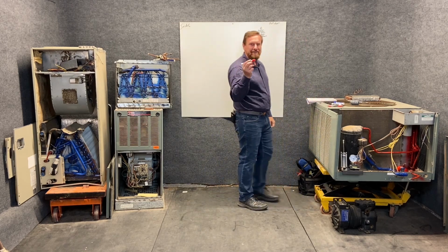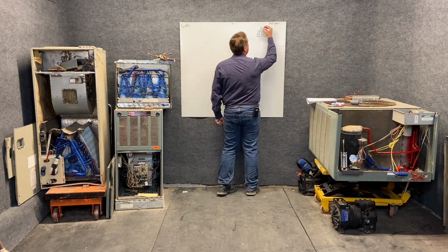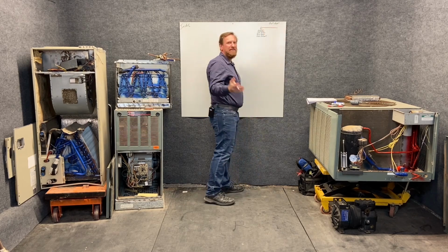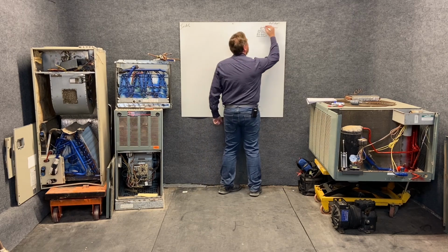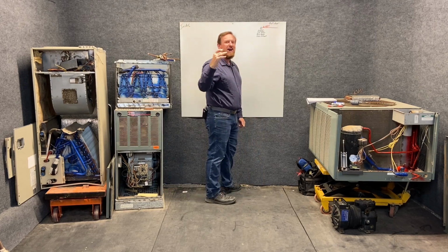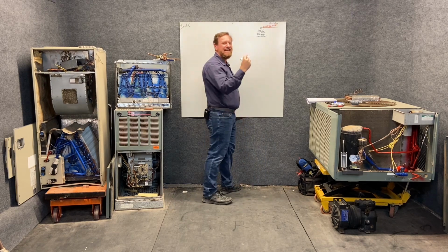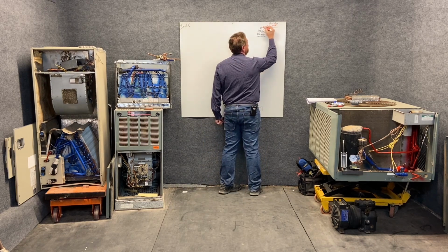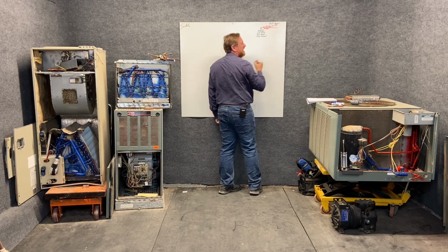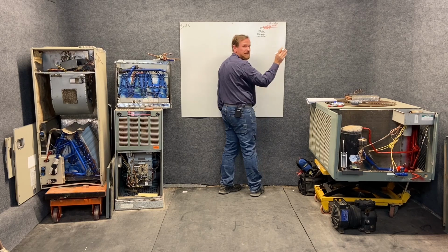Now we're going to get our red device. This represents high pressure. And this little bitty short line, the shortest line in the whole system, is going to be right here next. This little line, we're going to draw it in red. And remember, this component has two names. They are the discharge line, and it's also known as a hot gas line. The state of refrigerant in that line is a high temperature, so I'm going to abbreviate HT, high temperature. And it's a high pressure, so I'm going to abbreviate HP for high pressure. And it's a superheated vapor that we're going to learn about soon.